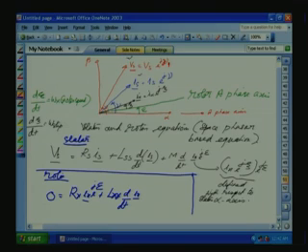So, the current which has a frequency of slip frequency will produce, due to the self inductance, a rotor voltage. Now, this rotor voltage we want to transfer to the stator. So, this is a space vector quantity. This space vector quantity, if you want to transfer to the stator reference axis, we have to multiply it by e raised to j epsilon.